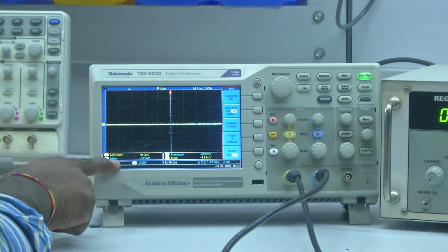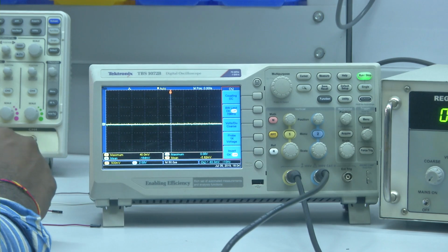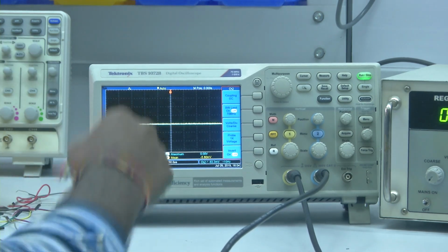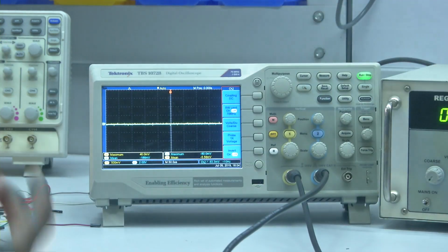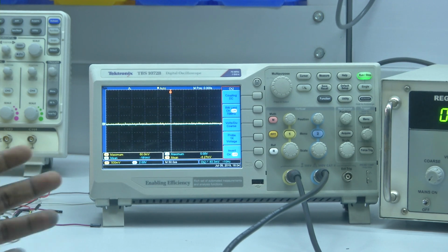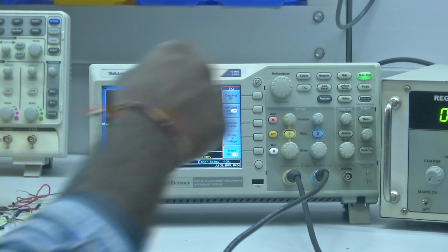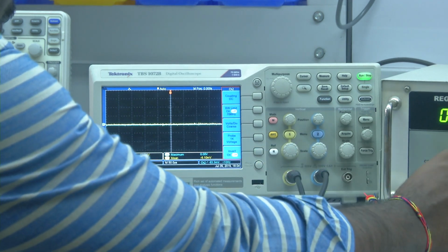If you observe carefully, one vertical box represents 500 millivolts for the yellow, whereas for the blue one box represents 2 volts. Since the gain is 10, if we provide 100 millivolts as input to the system, we will get approximately 100 times 10, that is 1 volt. But this is not the right way. Since we are testing our inverting amplifier configuration, we will provide the known input and measure the output side. Right, so let me provide the input voltage.